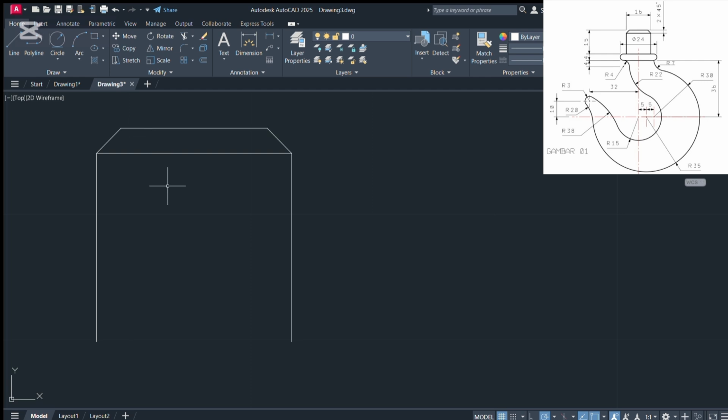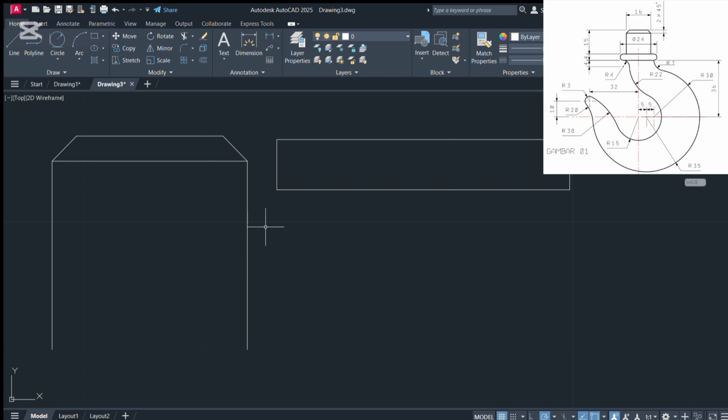Once that's done, we're now going to enter the rectangle command. You click on the rectangle, start to draw the rectangle, enter a distance of 24, press comma and click on 4, then press enter. Then something like what you're about to see on the screen will happen. Like you have this rectangle that is in length 24, and in the width it has a distance of 4.